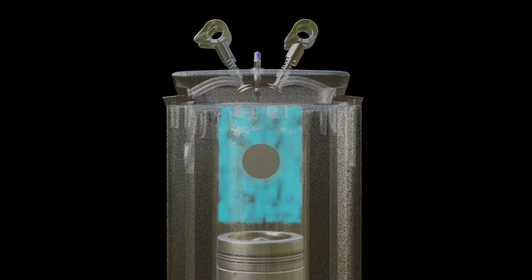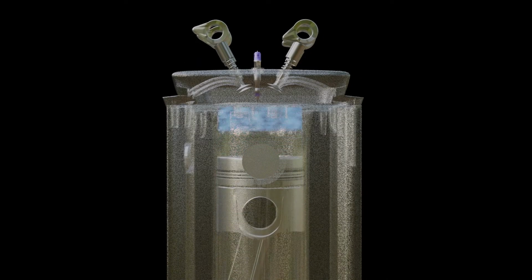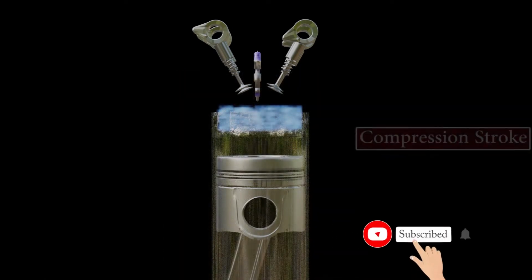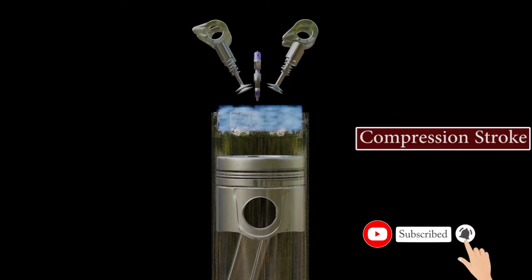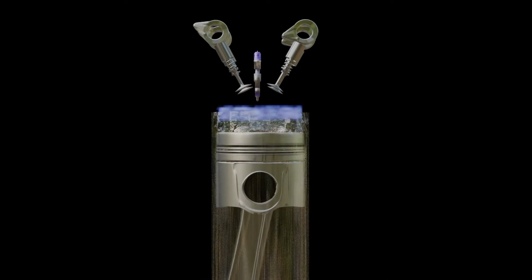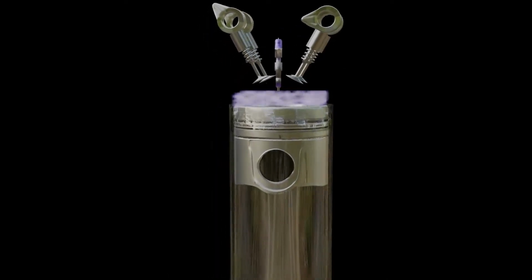During the return stroke, all valves are closed and air inside the cylinder is compressed. This process where the piston compresses air inside the cylinder is called the compression stroke, which increases the temperature of the air inside the cylinder. Fuel is injected at the end of the compression stroke.